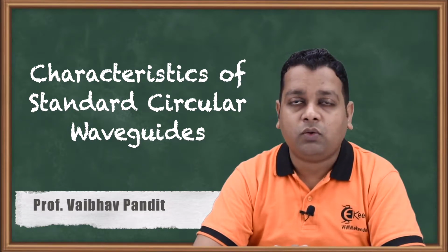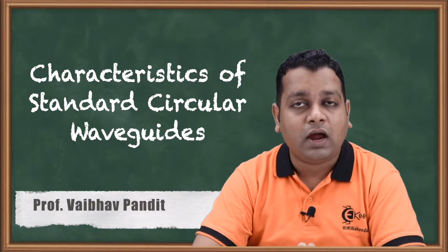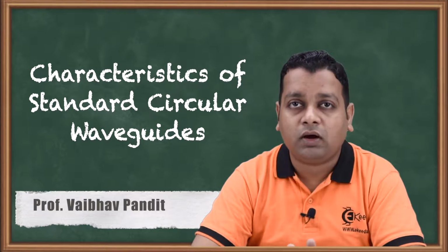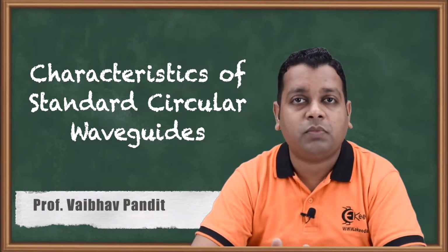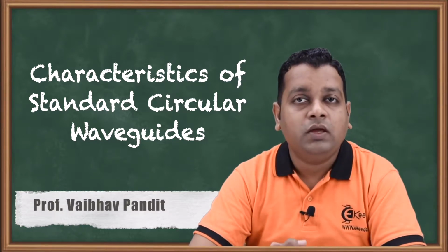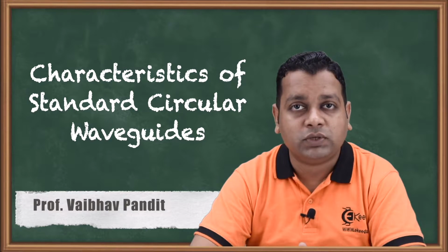So far in this chapter, we have gone through first of all the understanding of the conventional type of transmission line. For example, the coaxial transmission line, and from it we have a modification by removing the central conductor. We are obtaining a circular waveguide with a hollow cavity inside, which guides the microwave from one microwave component to another in a microwave system for practical setup. We have addressed several topics related to not having the ideal TEM mode of wave propagation, hence the alternatives in terms of transverse electric or transverse magnetic mode.